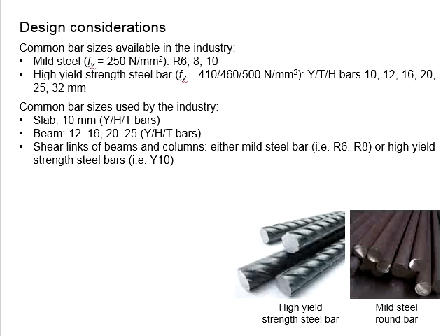You also need to be aware of the common sizes of steel bar in the industry. This is also a common mistake by students, not being aware of those, proposing a certain size of reinforcement bar which cannot be found in the industry, or using certain sizes which are not commonly used in the industry.